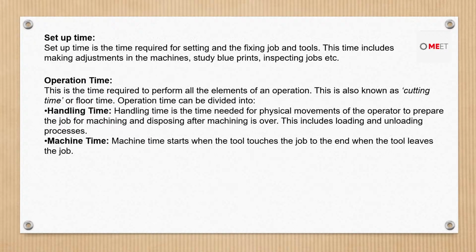Setup time itself, as you can understand, is the time required for setting up the tool and job into the machine. Operation time is known as cutting time or the floor time. Basically, operation time consists of two elements. One of them is handling time and the other is machine time. Handling time is the time needed for the physical movement of the operator to prepare the job for machining and disposing after the machining is over.